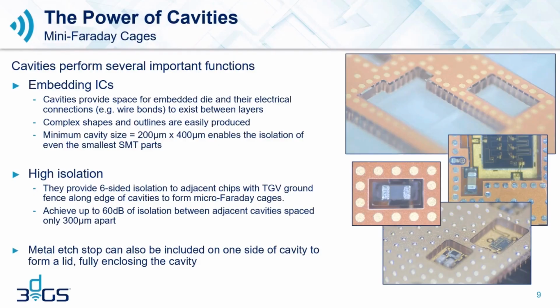solutions. So not only on these type of 3D-HI modules, but we also have substrate integrated waveguide components, which are used to create higher frequency millimeter wave type filters. And if we have two adjacent waveguides, we're able to measure isolation between those waveguides in excess of 60 dB. So many of our customers take advantage of these cavities, and they come for free. They're not an additional feature. It's just how you design the layout of the vias around the cavities that you see here.